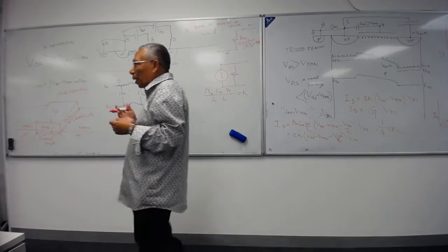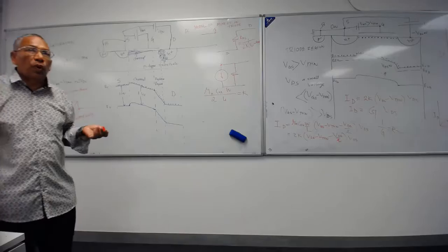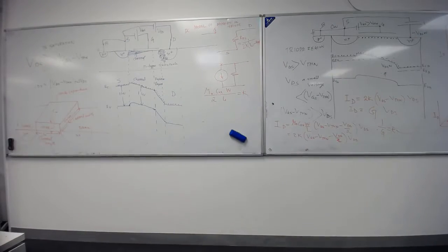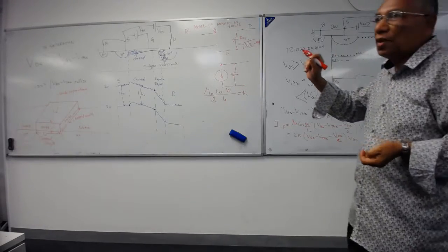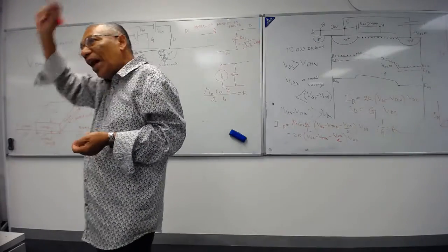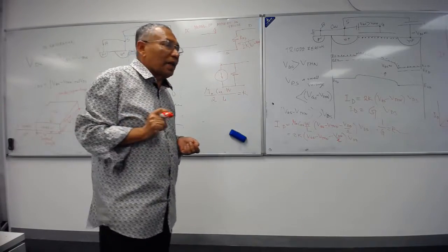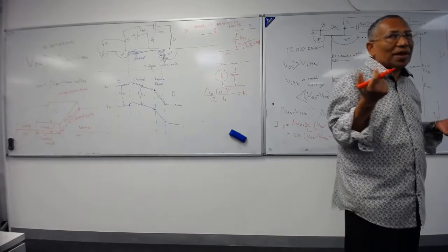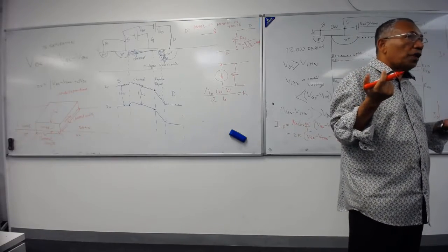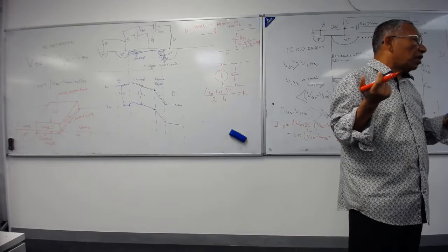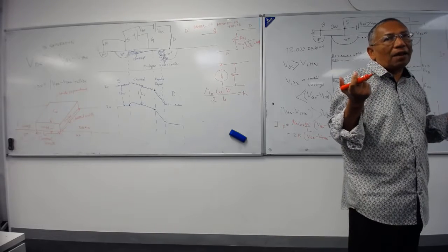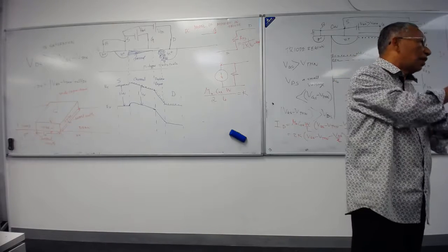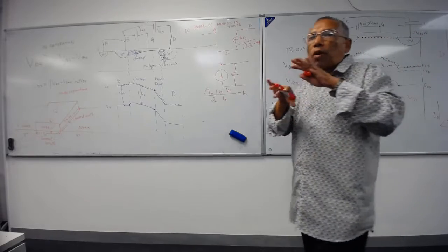So now the big question is, how do you do it? When we were doing BJT, it was very easy. We just draw a load line, we see where the IC is at, we draw what is the bottom, VCC at off, and then draw a line. And that will give you an idea of the load line. And then we know that if we use a beta which is very small, that will be the beta of a saturated BJT, which we said we pick 10 or 5 or 4 or 20, which will push the transistor into the saturation region. So we can solve the problem numerically.